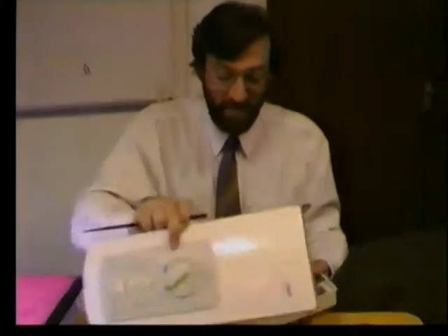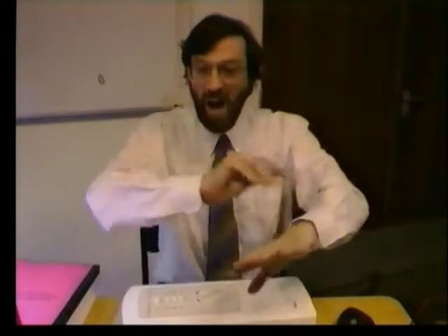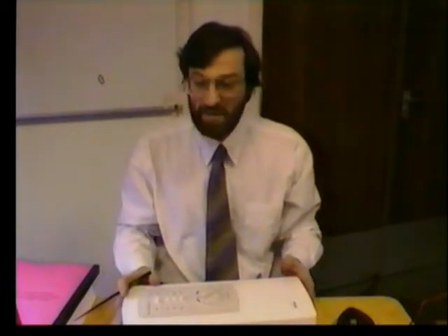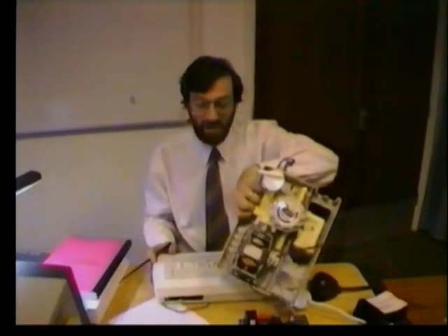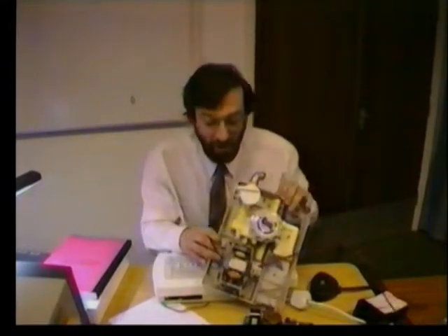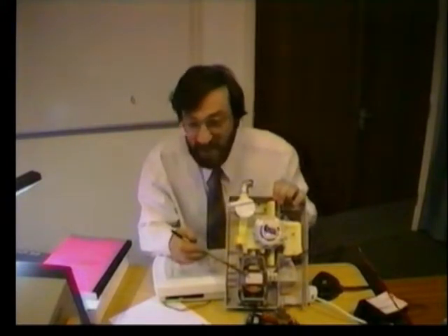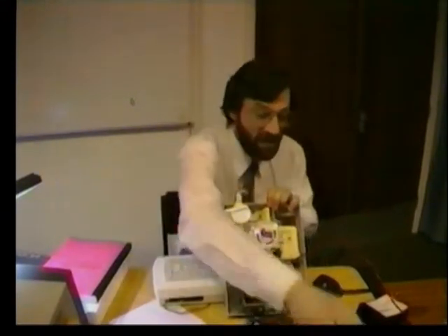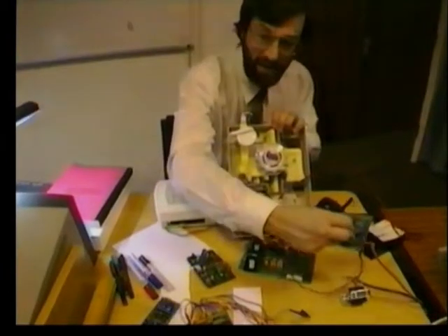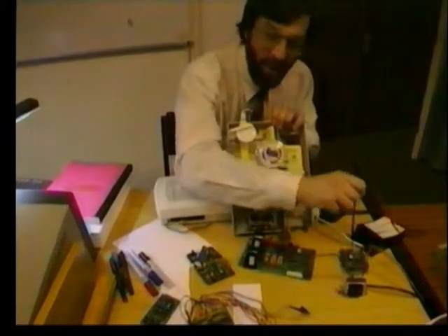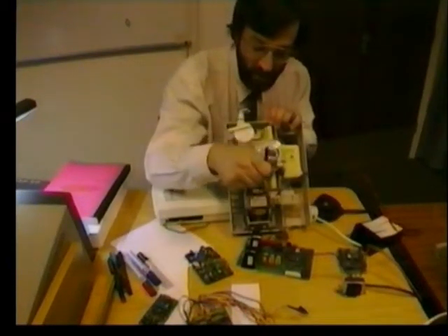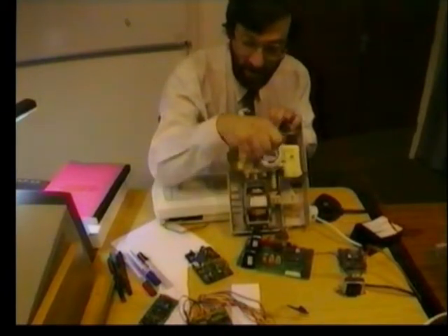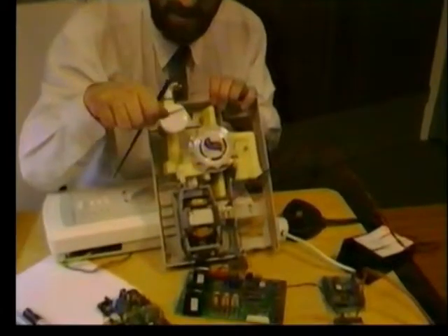So here we have before us a whole array of real-time systems. Domestic showers, 2 types of domestic shower. This particular shower unit, the first one I showed you, managed to control this AC mains motor using an itsy bitsy little controller such as this processor. How did that processor control the mains motor to change the speed at which this rotated?